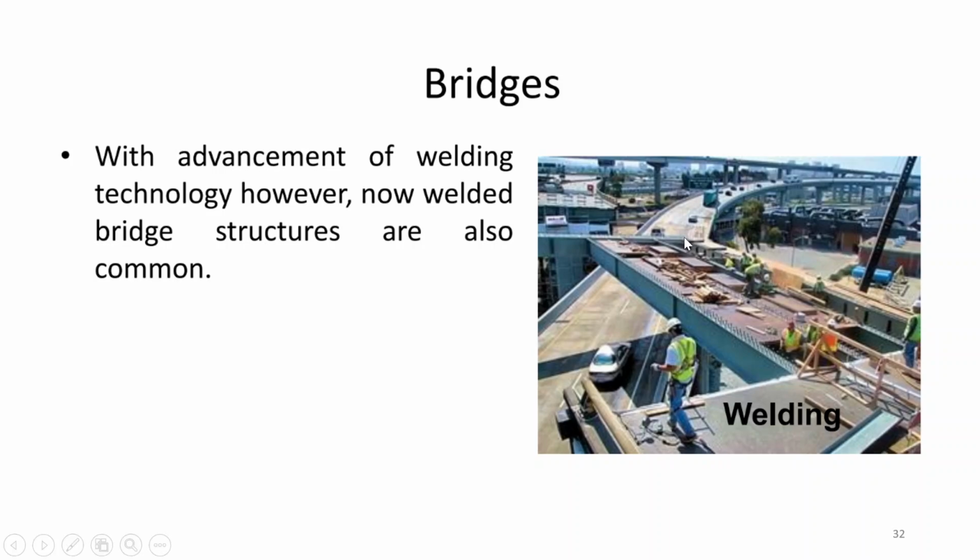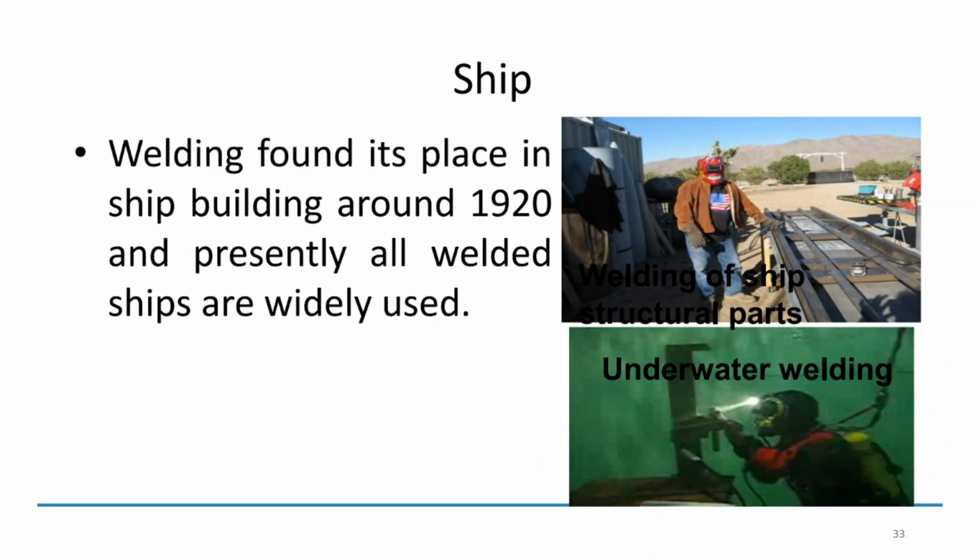Bridges, in case of bridges, with advancement of welding technology, welded bridge structures are now also common, and welding found its place in shipbuilding around 1920, and presently all welded ships are widely used. And underwater welding is also possible, in which case shielded metal arc welding is used. So the metal that is used as electrode will be made waterproof by some cover, it will be shielded.